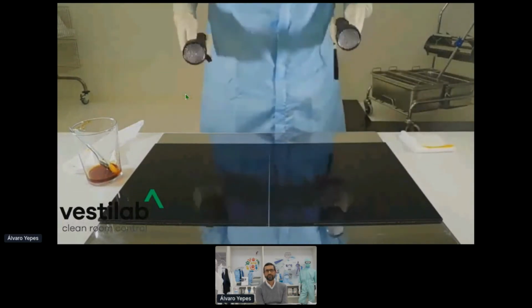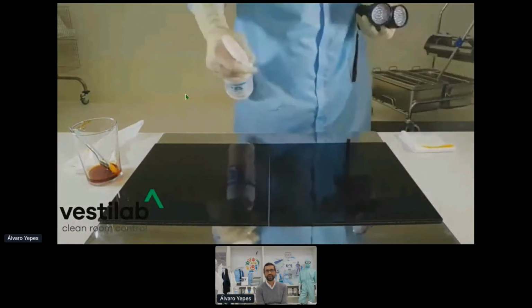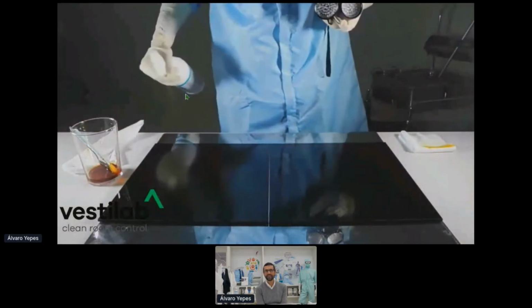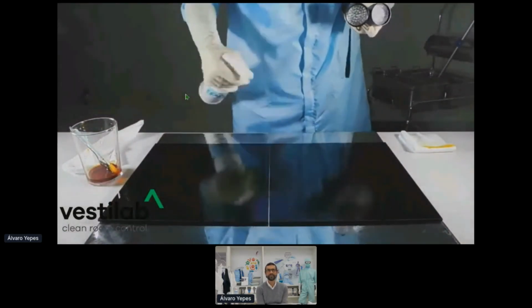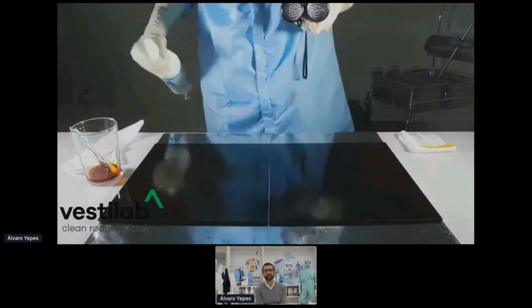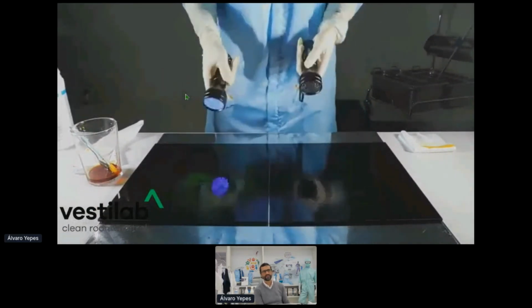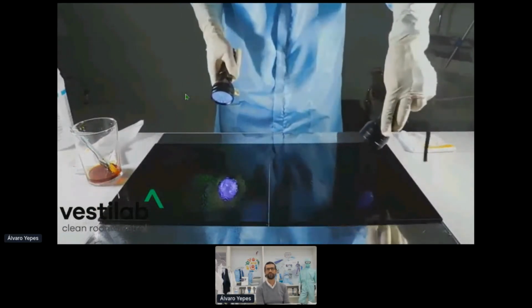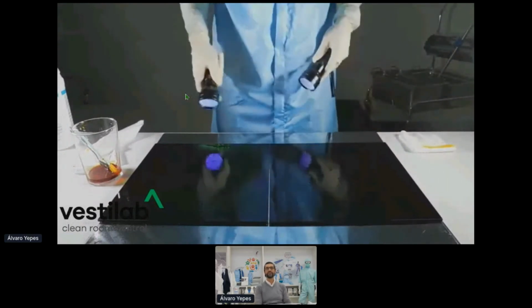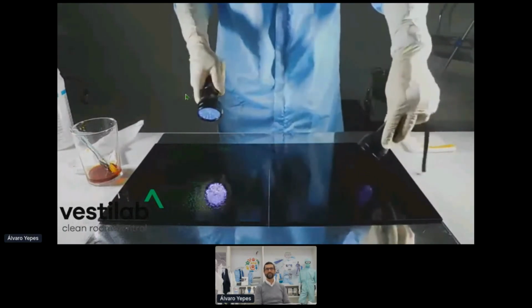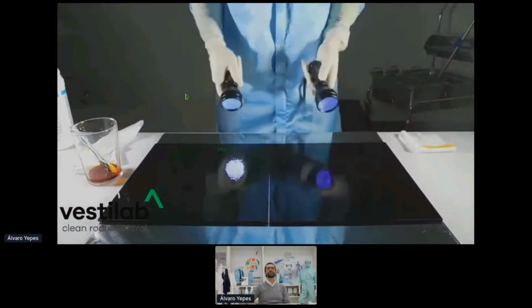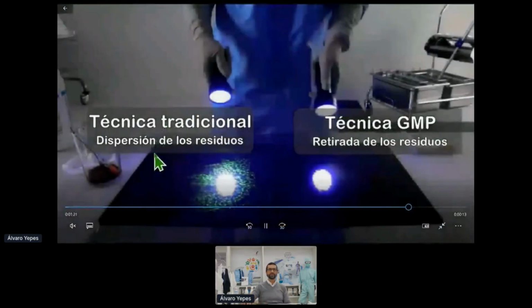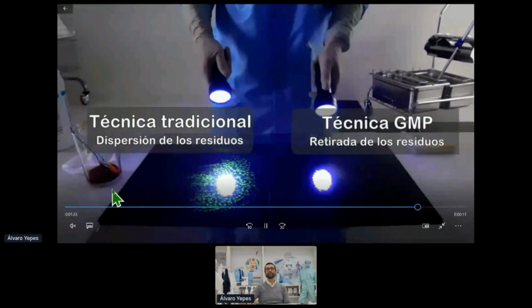So with this UV light, what we will show is how the surface looks. We use the IPA to highlight the color of the fluorescein, so it just brings more clarity to the UV. If you do this testing, it's very simple to do in the laboratory. It's very hard to film this and make it visible, but you can see straightforward the difference in the two images. So this kind of training is important for the operators.